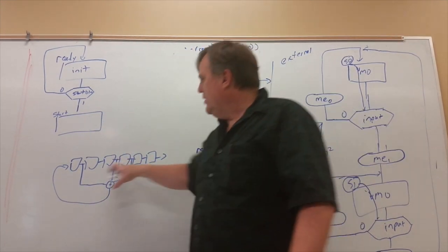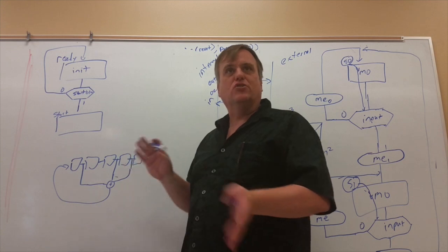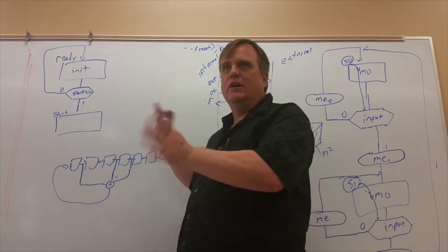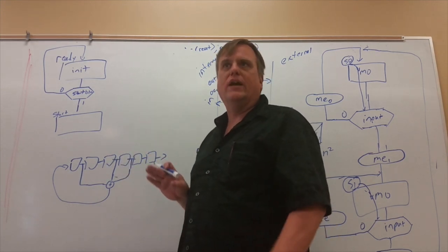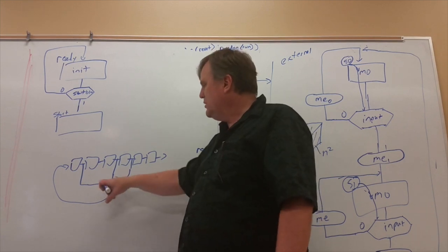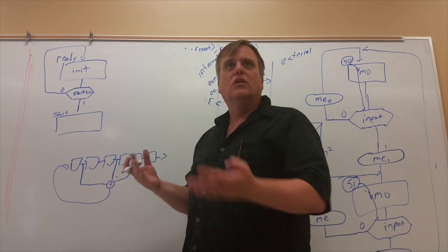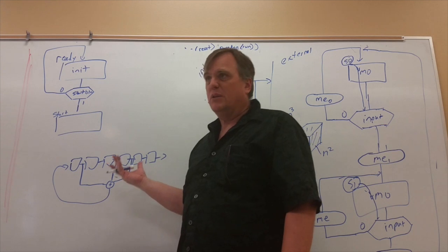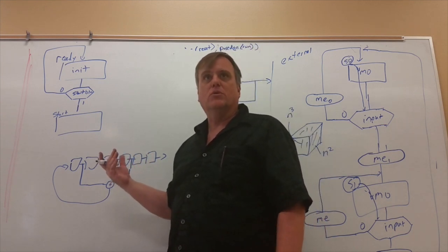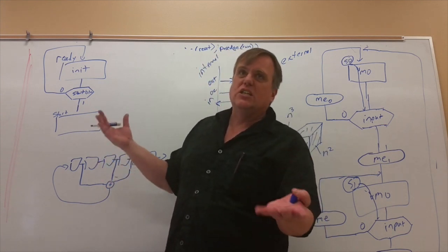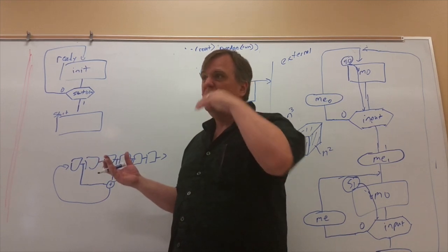Depending on where you set these tap locations and things like that, this is a classic, simple pseudo-random number generator. If you pick the right spots, you almost always want XOR. It turns out you don't need overly complicated ones. You can actually get pretty good random numbers. Not the greatest in the universe, but they're pretty decent.